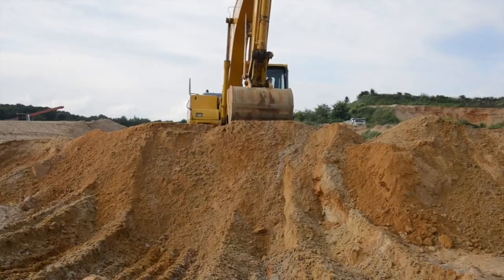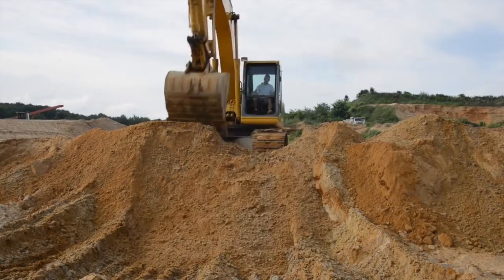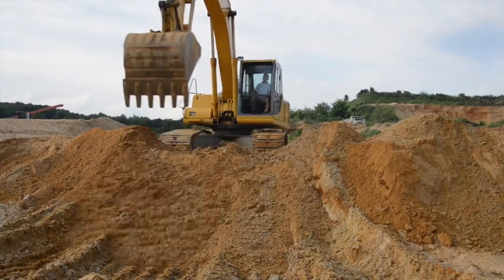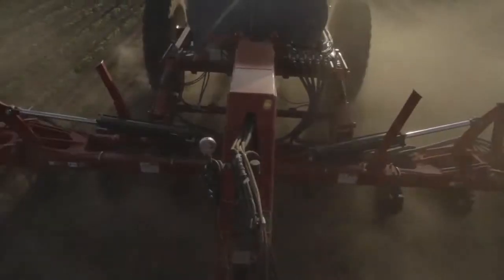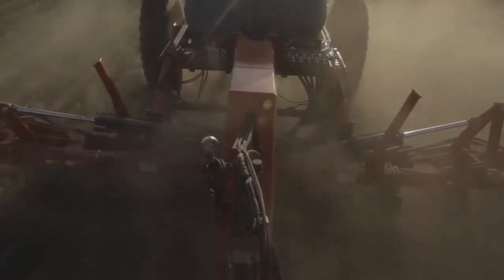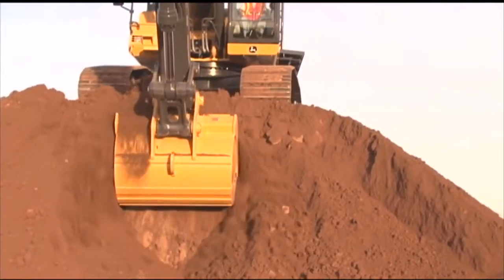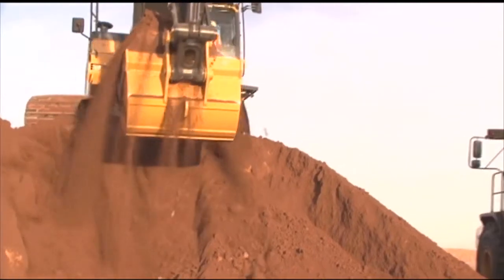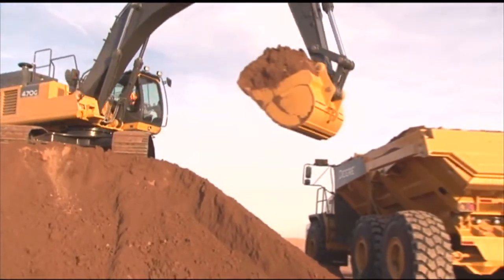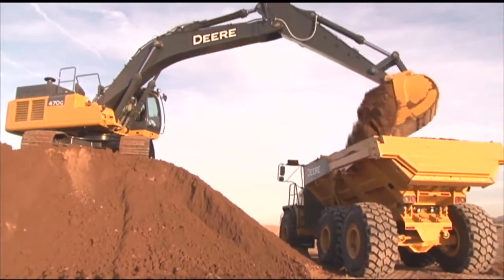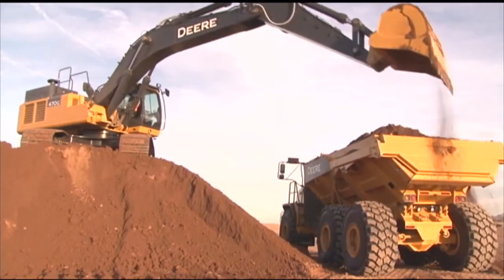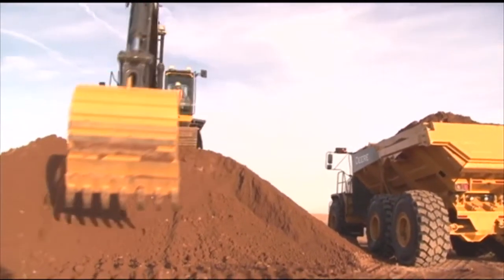There was a time when hydraulic pressures were much lower than they are today. Clearances between internal metal-to-metal surfaces were not as tight, and we were more concerned about contaminants we could see. We now need to be concerned about dirt and other contaminants that we cannot see, including particles as small as 2 to 5 microns. That small a measurement is hard to comprehend.